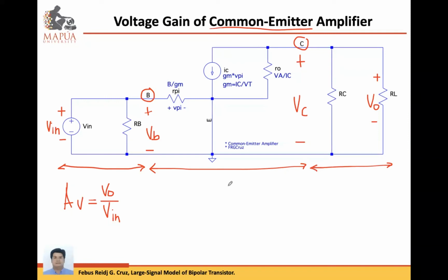All right? So using these three segments, we can also express the voltage gain. For the output circuit, voltage gain is output V out divided by input collector voltage. So you can write V out over collector voltage, multiplied by the voltage gain of the transistor. That would be output collector voltage divided by the input base voltage, so you can write VC divided by the base voltage.